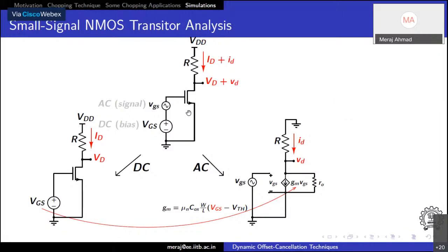If we do a static circuit like this, if we don't have any clock in it, it calculates DC once and then it calculates the noise and AC, or whatever analysis you want to do. In a switching circuit, we are changing the topology with time. First the input is connected in one way and then with the clock it is changing. So there we do PSS for calculating the DC operating point at different locations. In our case, we'll have only two different operating points since it's a clock with two levels only. So it's just two DC operating points.